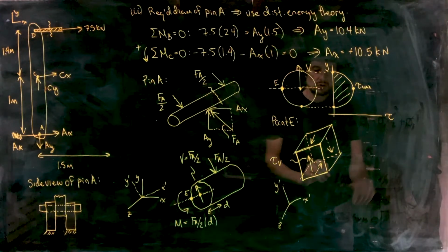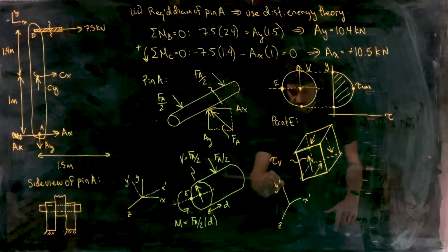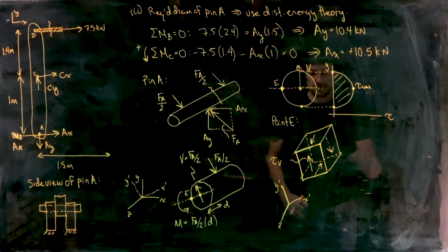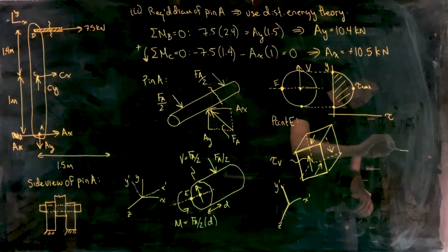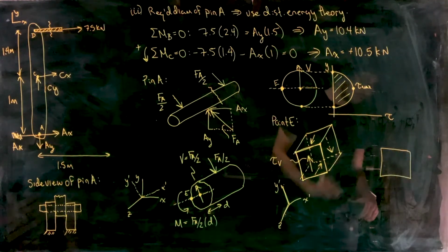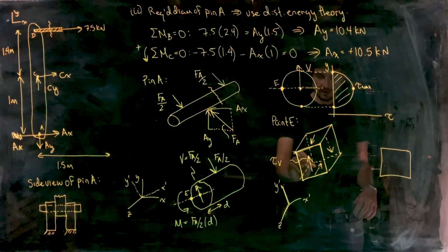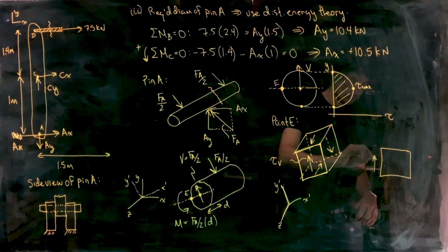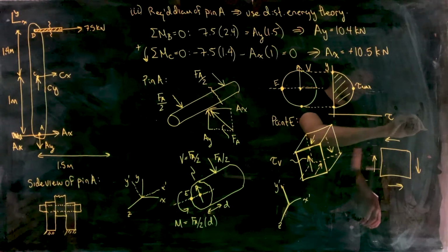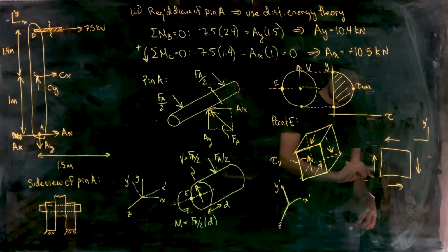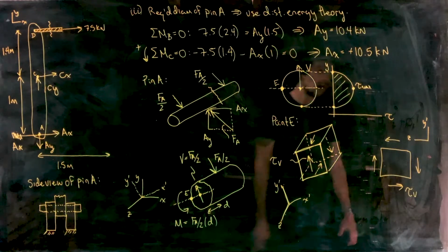All right, so our two-dimensional in-plane element, we want to draw that in the Y prime Z plane here. So looking at the element from the right-hand side, we'll draw this in a rotated form like this, just so that everything's nice and square now. And the shear stress that would have been on the front here is now on this side. Shear stress there, and shear stress there. So now, in terms of coordinate systems, we've got Y prime in that direction and Z in that direction. And this shear stress is tau V there.